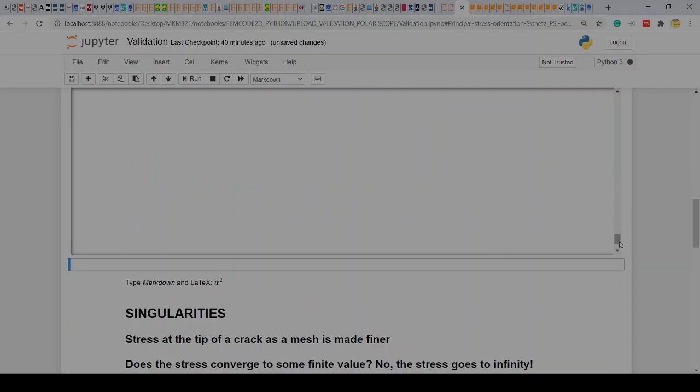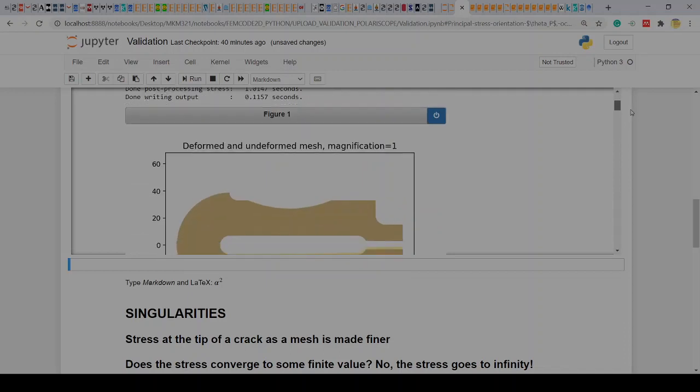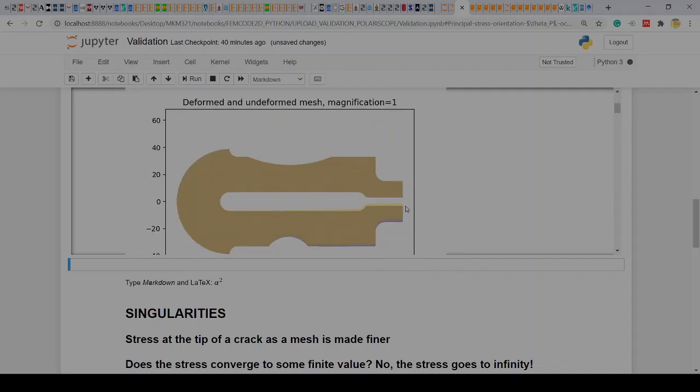So we'll now see the node that's moving visually. We'll be able to see that quite clearly. So there's the deformed, undeformed. You can see there that point now has moved up 2 millimeters. Beautiful. You can see that. And essentially we are compressing here, you've got some tension forming there, and then essentially some tension there because of those 2 points moving closer to each other there.